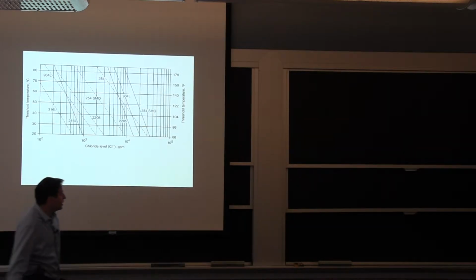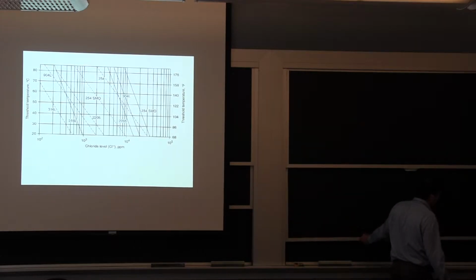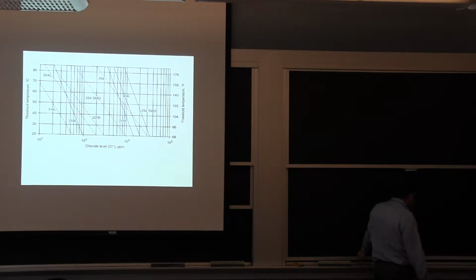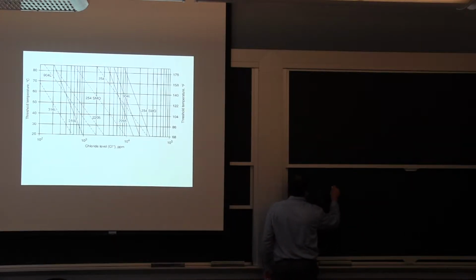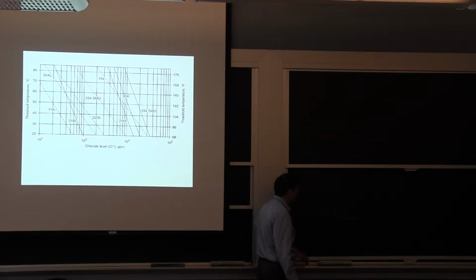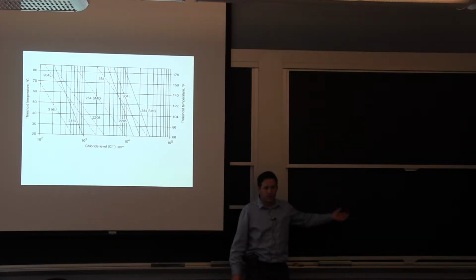It has nickel and molybdenum that both help to stabilize the passive film when you have chlorides. So 304 is kind of your basic stainless steel for general use. 316 is better. When you put the L, it means low carbon, and that helps for welding. So anytime we do welding of 316 grade, we use the low carbon because the carbon is going to combine with chrome otherwise and reduce your protection against corrosion.